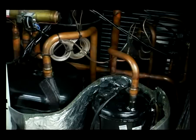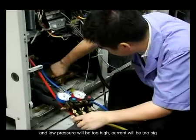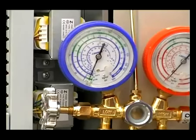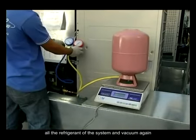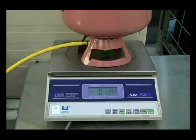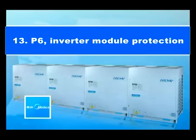If system is mixed with air or nitrogen, the phenomenon is that high pressure and low pressure will be too high. Current will be too big, compressor has abnormal noise, and the pointer of pressure gauge will be shaken. If there is such phenomenon, please discharge all the refrigerant of the system and vacuum again. Recharge the refrigerant after the whole system reached vacuum requirement. During the process, if refrigeration oil goes out, you should charge suitable volume of refrigeration oil.